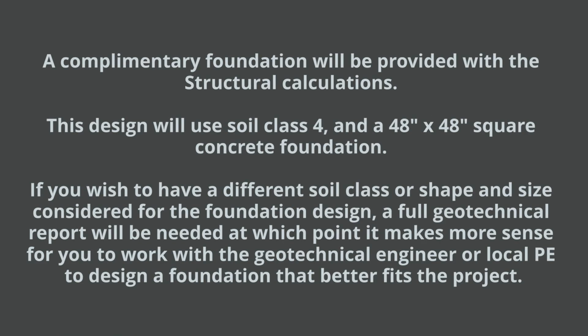A complementary foundation will be provided with the structural calculations. This design will use soil class 4 and a 4x4 square concrete foundation. If you wish to have a different soil class or shape and size considered for your foundation design, a full geotechnical report will be needed, at which point it makes more sense for you to work with a geotechnical engineer or local PE to design a foundation that better fits the project.